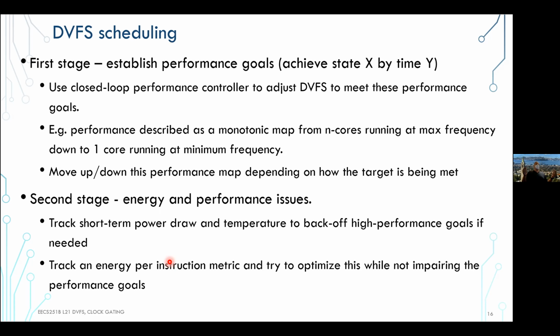Think of it in a way of, this is now at the higher level that we're talking about, where you don't have just one ALU on the chip, but you have a number of cores. And these cores could also be different size. We'll see later that Alder Lake, for example, has, as well as some of these, let's say M1, you have big cores, like let's say 4 of them or 8 of them, and then you have small cores. And you call one performance efficient cores and other energy efficient cores.